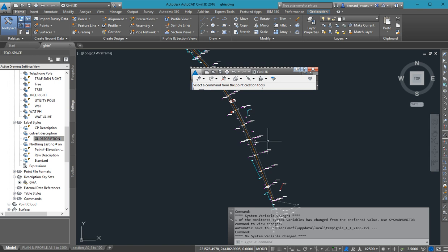So depending on the situation, but in this case, with an existing road, we will ignore the invert level. If not, we'll be having drops wherever there's a culvert. What it means is that at the end of the day, our earthworks volumes will be higher than normal. Please, are we getting it? Because wherever there is an invert, it will also have to compute from there.